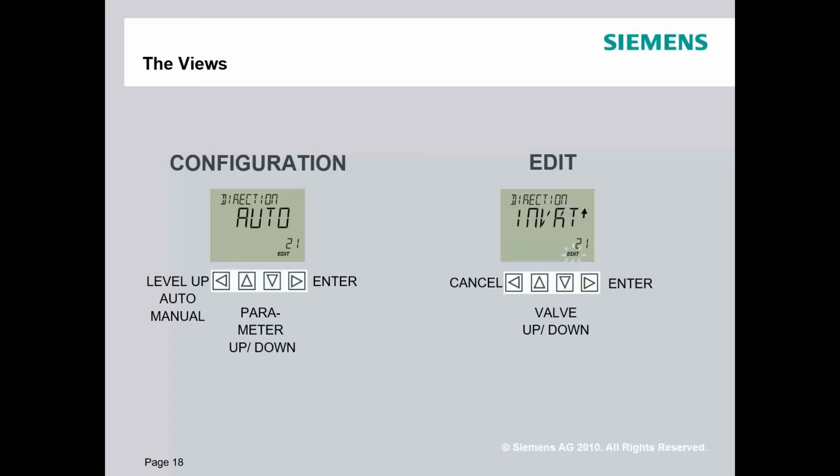And you really need to put a regulator on there, because, like Matt said before, all positioners, from the very first one to the slickest digital stuff, do one thing really well, and that's to correct the error between valve set point and valve position. Well, it's going to keep loading air until it corrects that error. What if it can't correct the error? Something's in the valve, something's blocking it.